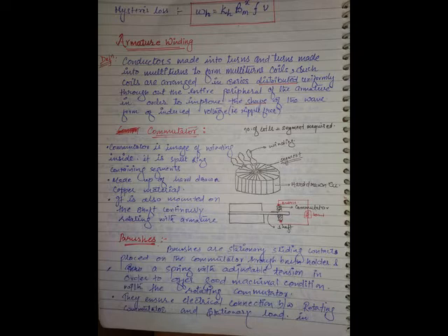There is an armature, you are getting voltage. So anywhere at this point or at this point, you have to collect the voltage. So you have one neutral zone. This is the neutral zone, and where this is the EMF is maximum. Inside, the armature conductors are in series. Don't divide them. Don't think that the EMF induced in this coil is 0. So when you keep the brush across the brushes, the voltage is 0. Don't think like that. Is the point clear?